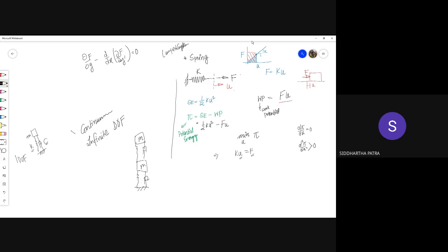Now you can also contest this term continuum. We have been repeating this term since the last class. Is the building material really a continuum? No, it's not. You can think of the bricks, you can think of the metal in them, like the steel rods that are there. All of these are made of grains, and grains have grain boundaries, hence the discontinuities are there. So obviously it's not a continuum.